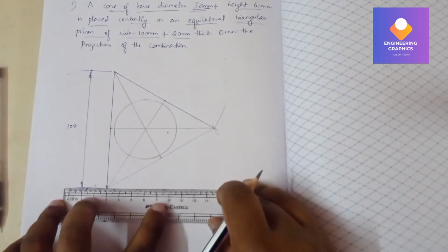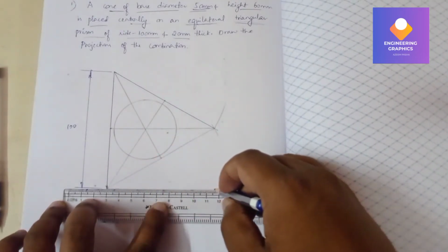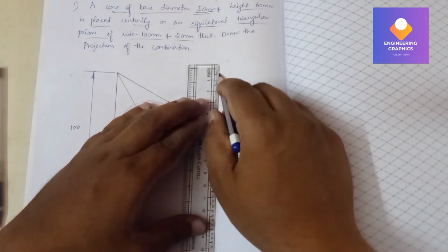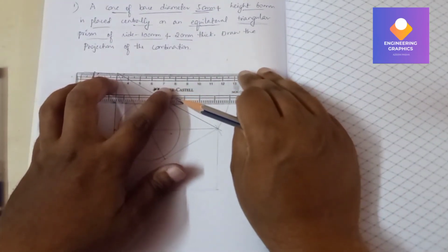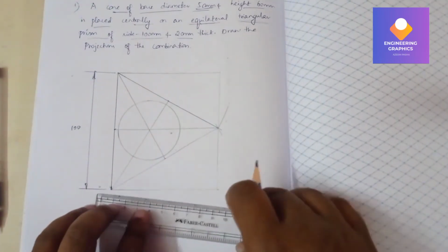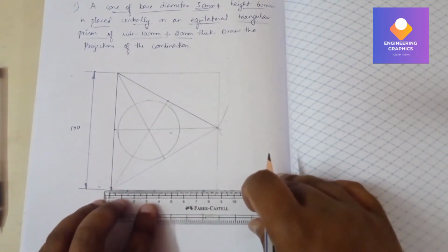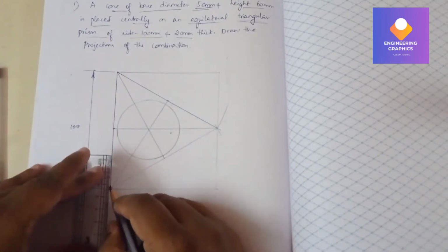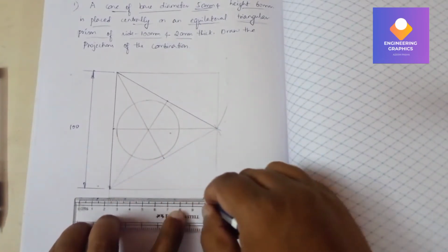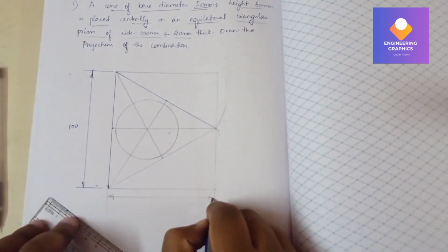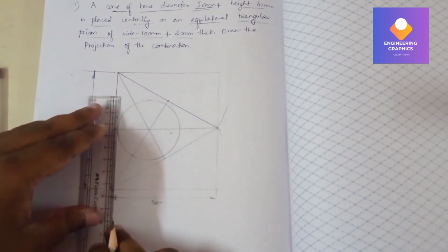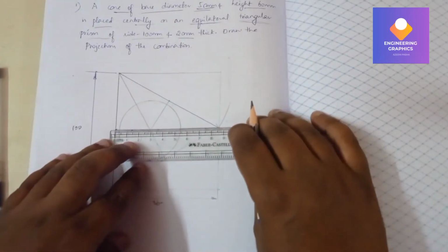Okay, now we will construct the box here. Using the boxes only we will be constructing the isometric projection. So we have to construct the box here for this triangle and circle. Okay, so dimension, we have one side 100 and the other side, I think it is 86 mm. Okay, it is 86 mm. So the distance between the end of the circle with respect to this side, I think it is around 3 mm.